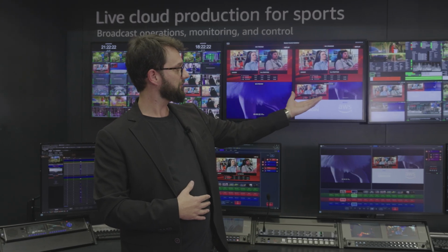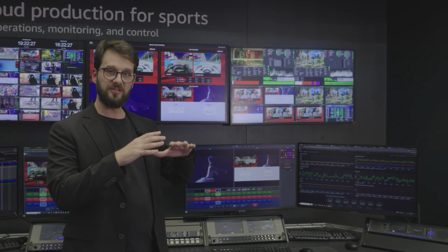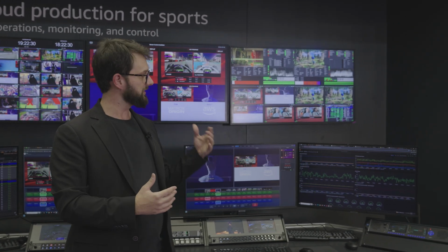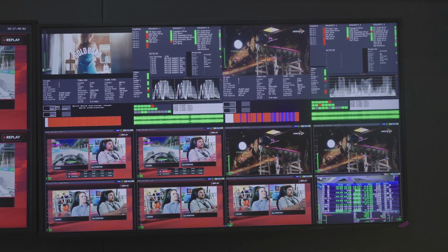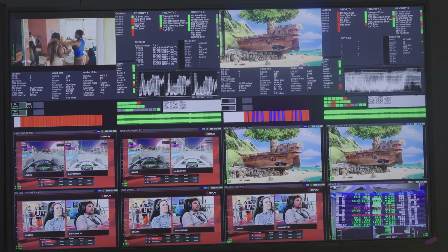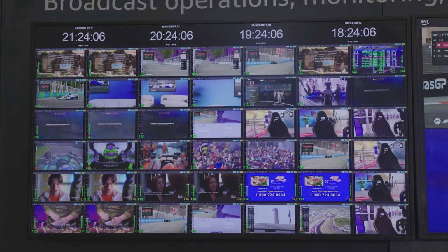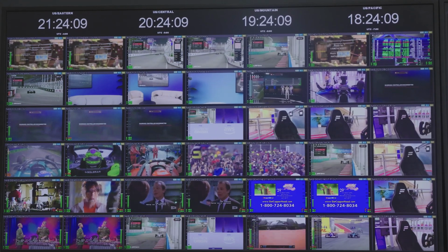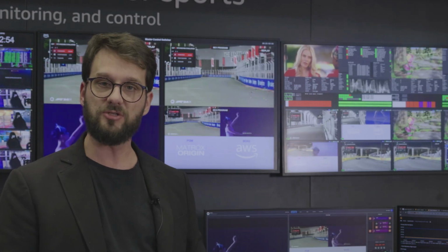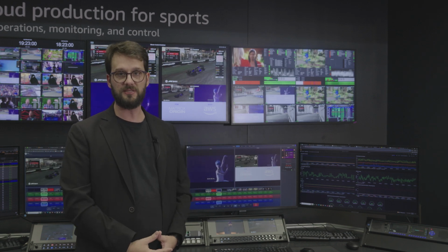The last screen we have here is more like a distribution type of multi-viewer, so the feeds that are ready to be delivered to the viewers pass to a last final check. You guarantee that all the parameters are correct, the transport streams are good, no alarms, and after that, we are sure that these feeds can go over to the viewers without any disruption. We also have distribution over internet using services like MediaConnect to deliver that to international markets, but we also are doing a real terrestrial distribution here, delivering this content over the air, demonstrating the capabilities of the ATSC 3.0 distribution system.